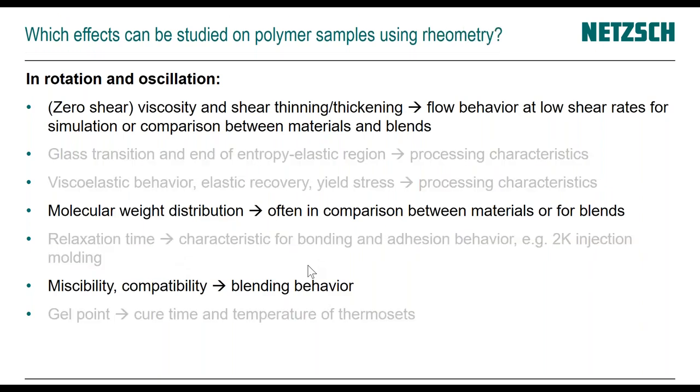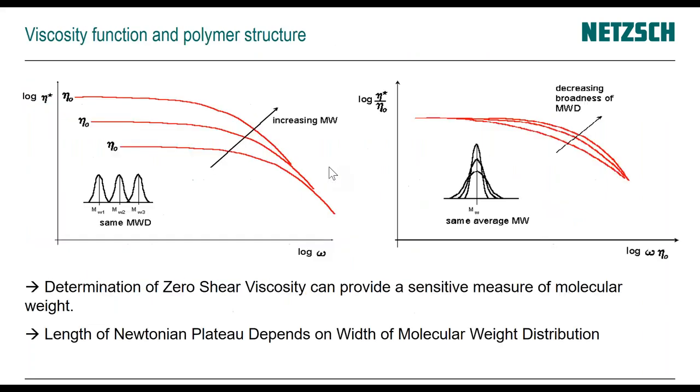And gel point for thermosets. So in the next couple of slides, I want to focus on the zero shear viscosity, molecular weight distribution, and miscibility. For some, I'll only show you some schematics because we're not always able to share what we measure for customers, but I still wanted to give you that information. And that is how the viscosity function tells us something about the polymer structure.